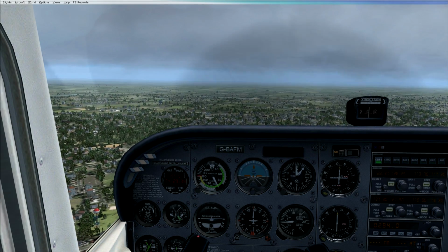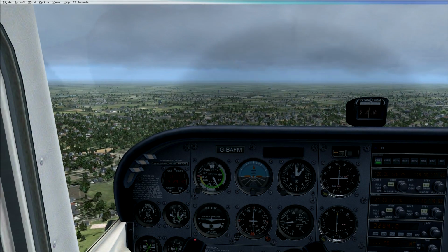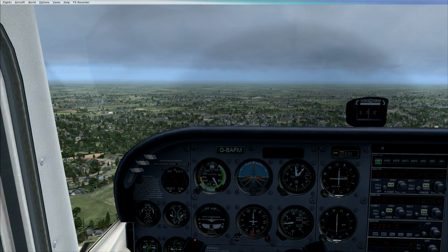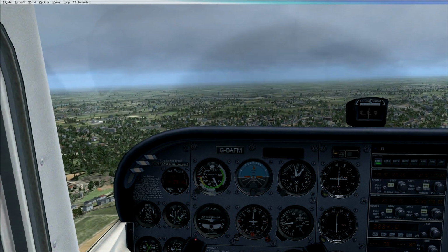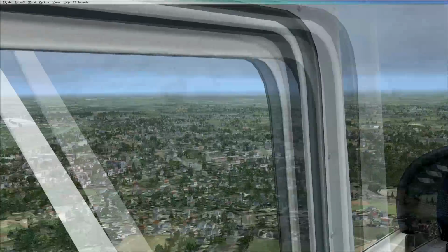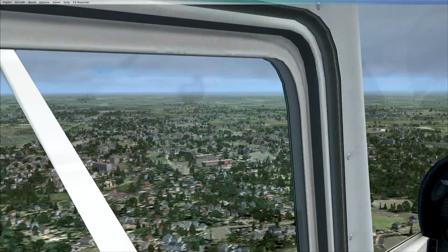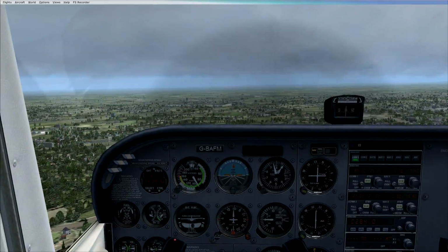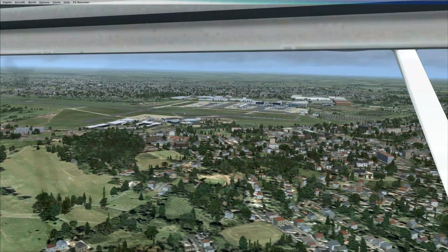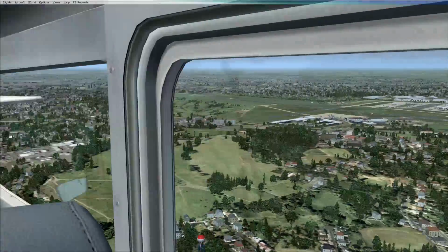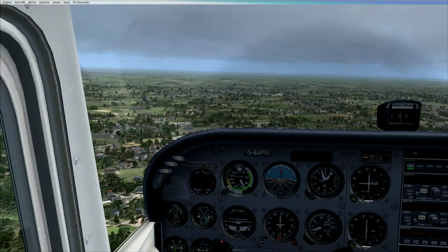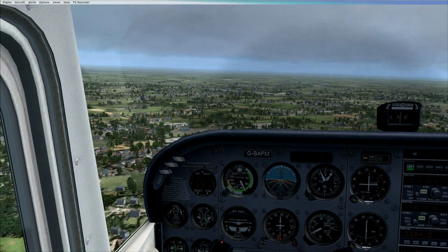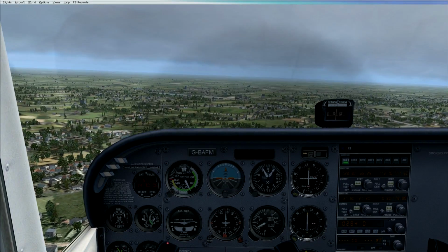So reviewing it, we took off, we turned left onto what's called the crosswind leg, and we're now flying downwind, which is parallel to the runway with the wind roughly behind us. Now there's not much wind. The next point we're looking at is when the runway threshold where we're landing, which is where the white marks are, is approximately 45 degrees behind our wing. That gives us our position that we ought to be looking at to start our left hand turn onto base.